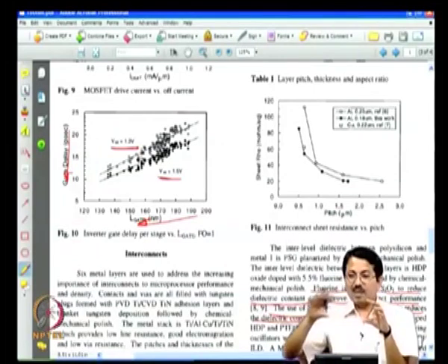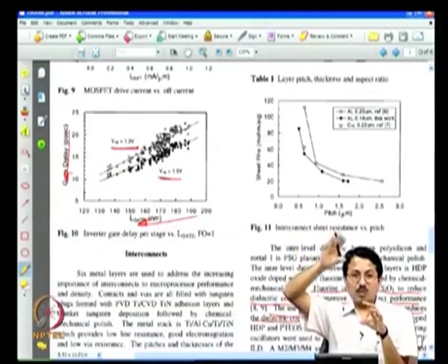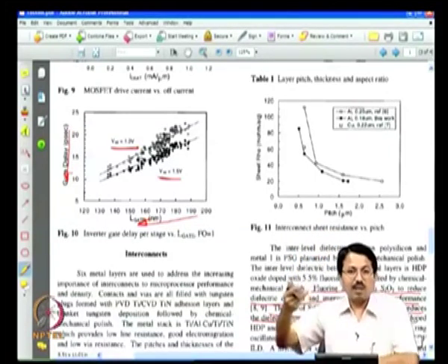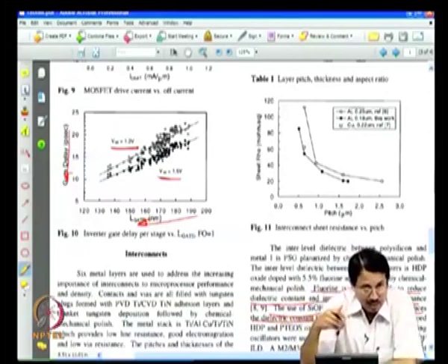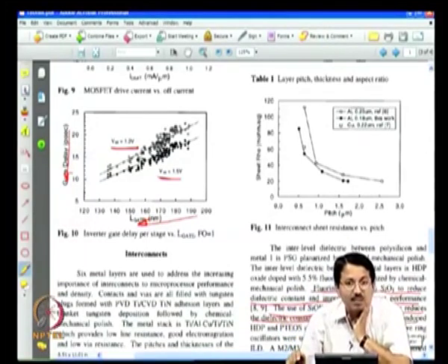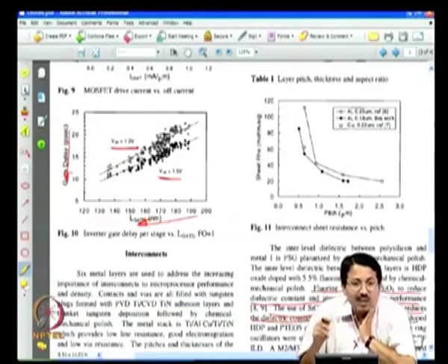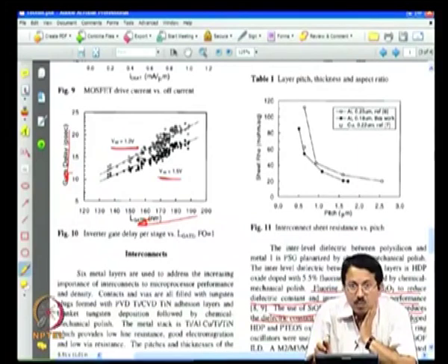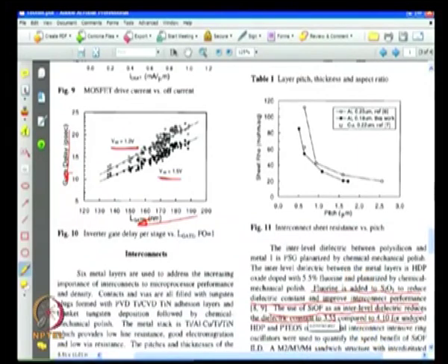You already have a metal line, and on top of the metal line you have to put oxide. So there is no silicon to grow oxide; you will have to do a chemical vapor deposition of the oxide, and invariably these oxides, which are done at low temperature because you already have a metal, tend to have a little higher dielectric constant, hence of the order of 4.1. After fluorine doping, it comes all the way down to 3.55.